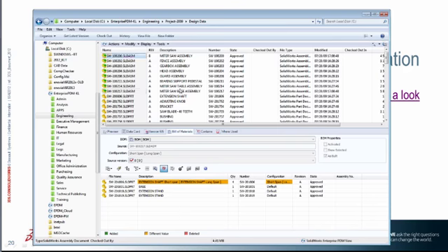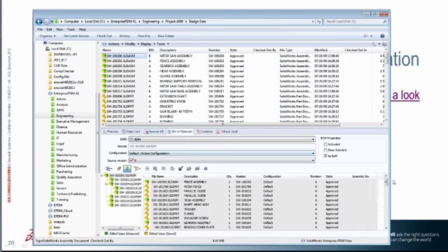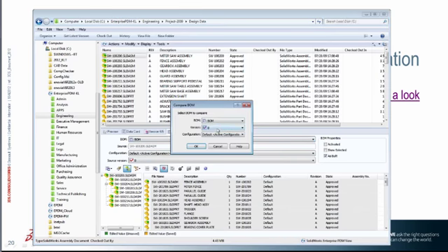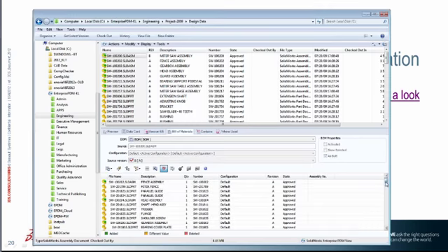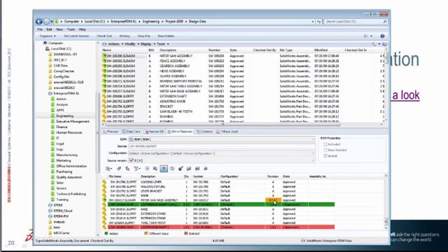So if I go back up to this assembly, which is not a real large assembly, let's say I want to see what the difference is between revisions, which is another thing we can compare. So if I'm at revision B, but I want to look and see what it was like at revision A, I can look at that comparison. And as I scroll down here, I can see that I had a different revision of this assembly. This part was added in revision B, and this part was eliminated from revision B. So we can tell which items were added and which were taken away.